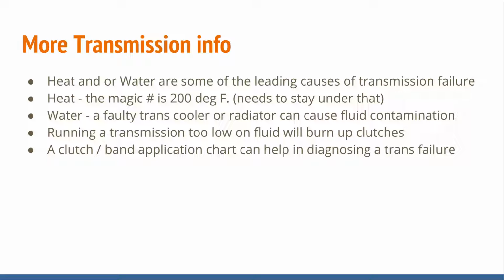We don't have second gear in the trans. All of a sudden third gear is commanded and it engages third gear, and then finally fourth gear is commanded. Nothing happens again in the transmission. That points us in one direction or another. We pretty much just said, okay, the computer's telling it to shift, the transmission is not. So we just narrowed it down to a transmission problem rather than a control problem.